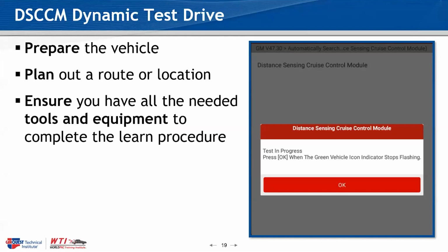And I will answer a couple questions about the aftermarket thing real quick. Just keep in mind that an aftermarket scan tool is simply requesting that a module does something that's already in the module. The software and programming on how the module is going to perform this calibration is in the module itself. That's something we probably just programmed into it during our SPS programming procedure. So all we're doing with the scan tool is requesting that the module do its thing. I'm not saying that every scan tool that has this button will work, but if it has the button, you press the button and it correctly sends the correct command to the module, then from that point forward, it's all on the module.